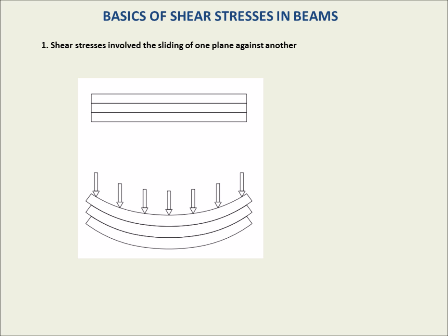Now, what is particularly apparent, especially on the ends of the beam, is that these 3 layers that make up the beam have slid relative to each other. So at the plane that forms the point of intersection, the two planes on the top and the bottom, let's say, there's been relative sliding. This is how the shear stresses get introduced. In a beam where the planes are integral, made up of a continuous homogeneous material, the stresses that keep the layers together are the shear stresses.